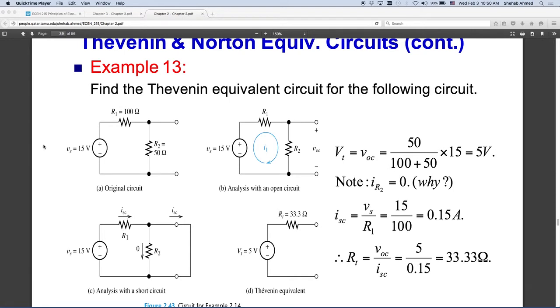With the Thevenin equivalent circuit, the result that we want to achieve is to put this big circuit in a box and then bring two terminals out. From these two terminals, I would like to build a representation for what's inside this box. Why? Because if you want to connect a specific device to your big circuit, you want to look at the effect of that big circuit on that specific device. You don't care what's happening inside that big circuit. So you come up with what is called a Thevenin equivalent circuit for that system.